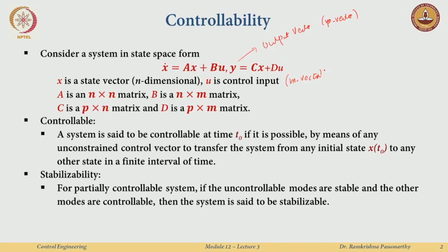Okay, so what else can we do now? So just given a system x dot equal to Ax, I know how to find out stability. I also know how to go from the state space representation to the transfer function. This we had learned in the earlier lecture. So I'll just write down the formula for you again. G of s is C (sI minus A) inverse B plus D. Okay, so this has all been good so far.